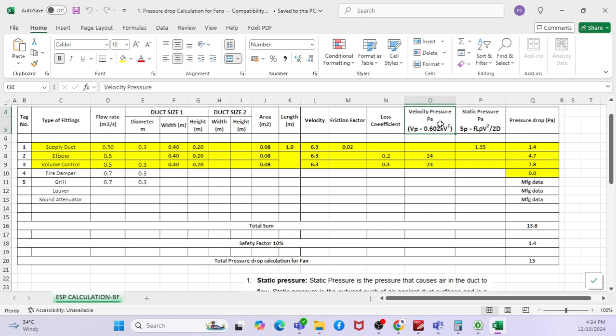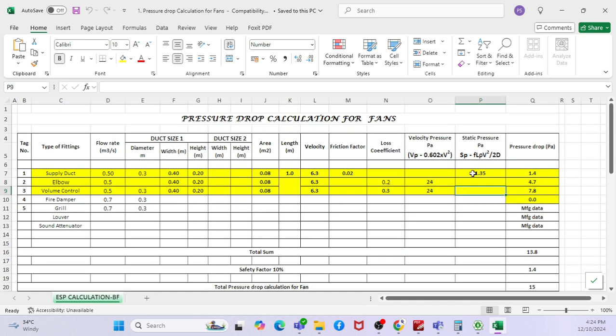Also, you can go through it, and you have a design criteria. There are different types of duct designing methods. One is the equal friction method, the velocity reduction method, and the static regain method, right? There are three different applications, and based on that you can size your duct. When sizing, you mean three different applications, you mean to say different pressure per Pascal per meter values, right? That is what you're trying to say, right?